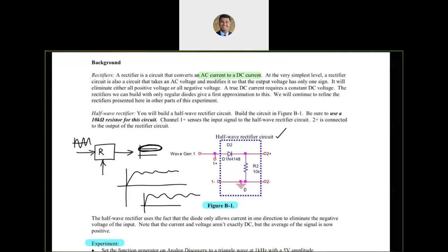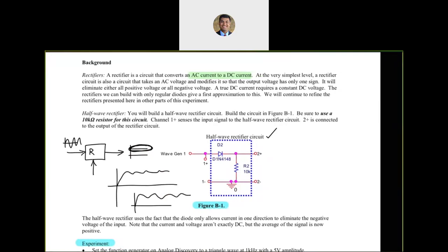What do we have here? We have a circuit. Let's see, I'm going to erase all of this and get into a circuit here. The diode and resistor, the places have been exchanged, but they are still in series, so it really shouldn't matter what is happening. It still requires 0.7 volts to turn on. All the remaining voltage goes to R2.